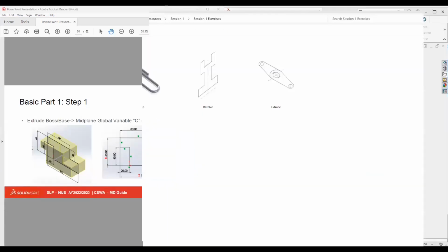Okay, in order to make your first sketch, under the sketch tab, you click on sketch. Then the software will prompt you to choose which plane you want. For now, we'll be using the front plane. After you go in, we should do a rough sketch of your design. We don't have to do the exact dimensions first, because doing it exactly is very time consuming.